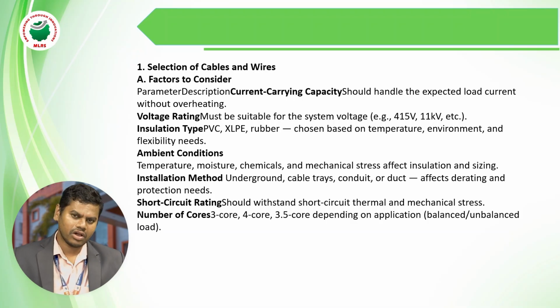Next, after current carrying capacity, we choose the voltage rating. How much voltage rating? It must be suitable for the system voltage, for example 415 volts or 11 kV, etc. So this voltage rating is applicable to selection of cable, and this is also one of the factors to consider.